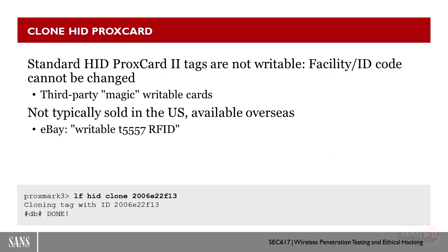We can also write that data to a new card with a special HID-Prox2 card. The problem with the cards as you buy them from HID Global is their T5557 implementation doesn't allow us to write data back. They are read-only. But because they are using readily available devices that are used for other purposes, we can buy cards from other manufacturers that have left them read-write, and we can now write back to those cards with our own data, with third-party magic writable cards.